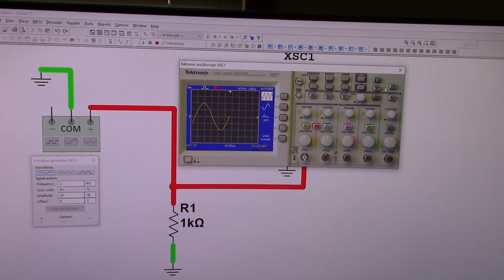How you can do that is, you see up here it says measure. If you click that, you get the values here. Now it says none, none, none. That's because none of these things have been set. So let's do peak to peak volt. Well, let's see what the first one is.